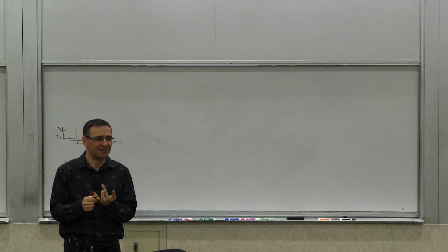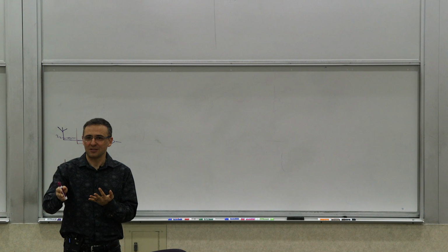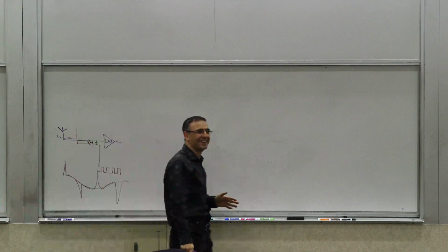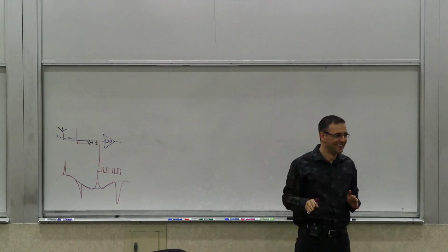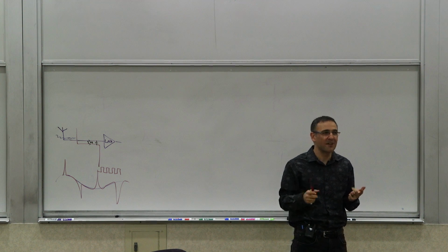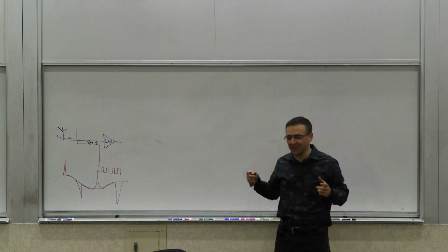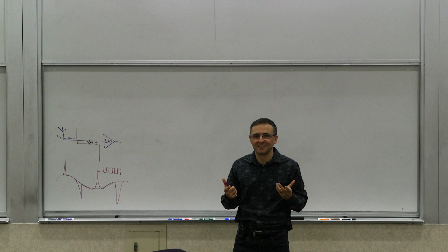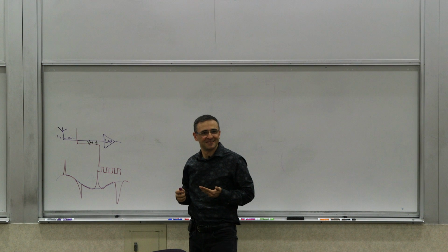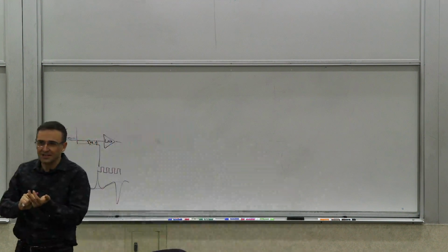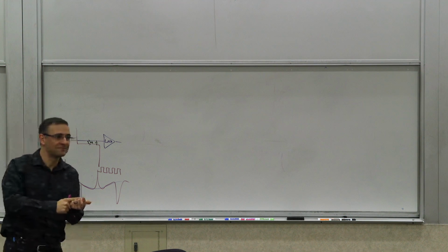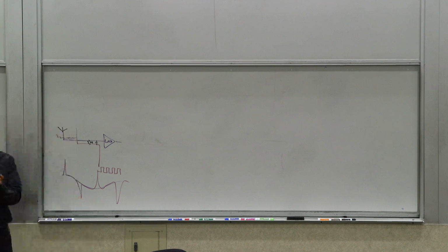What is the other thing that you can do? You can tell the person, well, cut it out. Yes. Right? Just reduce the source. Reduce your sensitivity, reduce the source, or the third thing, which may have been essentially a combination of all that, reduce the coupling. Go sit somewhere else. Put a wall between you. So reduce the coupling, reduce the signal source, or reduce your sensitivity to it. I can't think of anything fundamentally different.